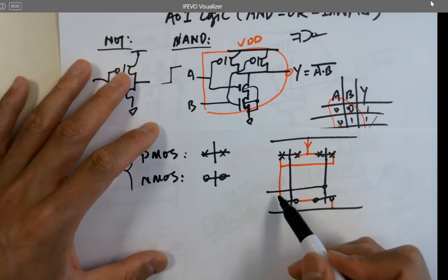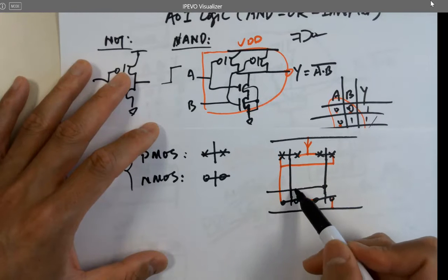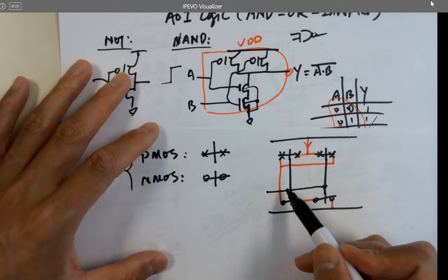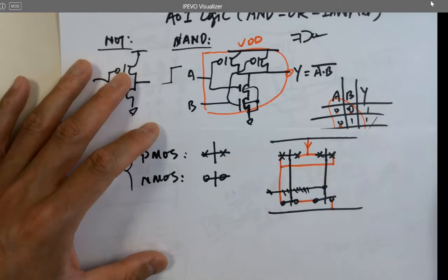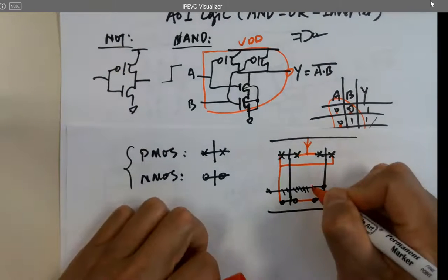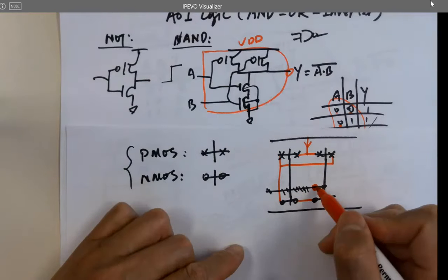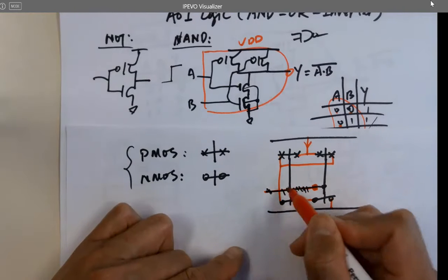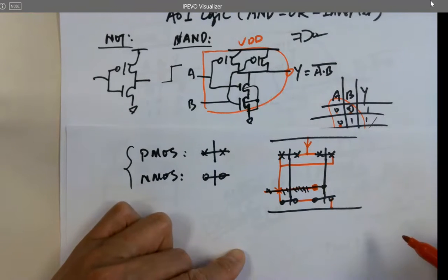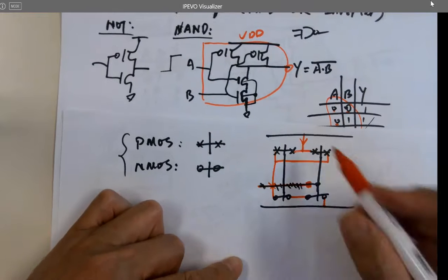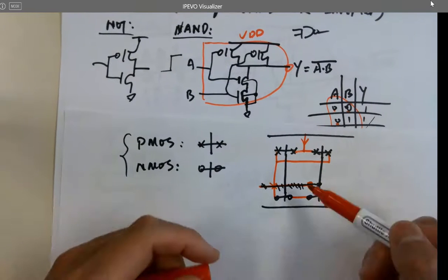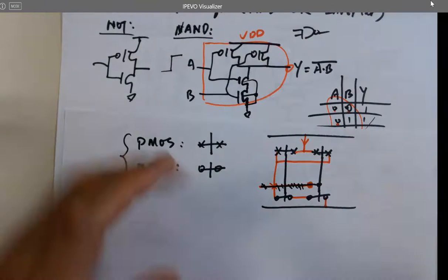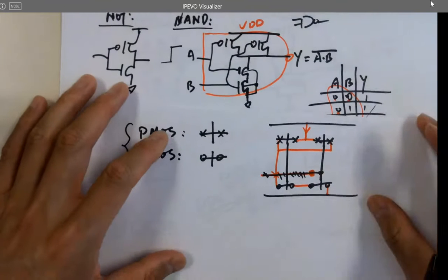So this is a problem, because this is shorting to this poly. Now you're thinking, let's go up to metal one. I'm going to get a via here, directly introduce a via, get a metal one, then short it. So the initial design here is not really optimized. It won't be an issue. You can go up to metal 2, yes, but there's a better way to design it.